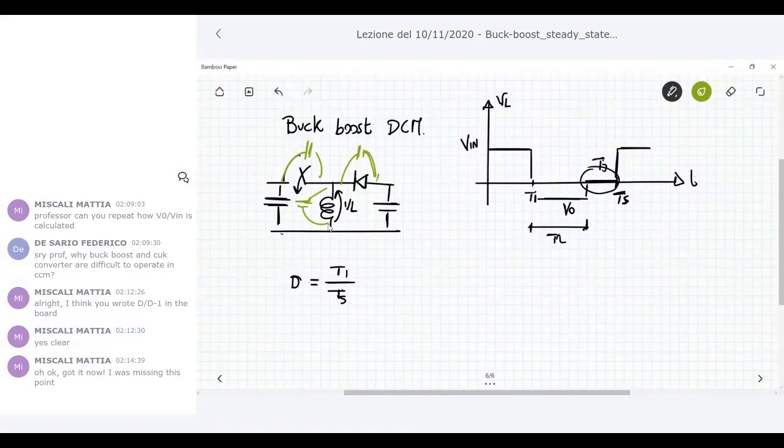This was observed in the lab, for example, for people working on the buck, but it always happens due to the fact that in that specific situation you have a resonator. And so you have to damp this oscillation by using some specific circuits.